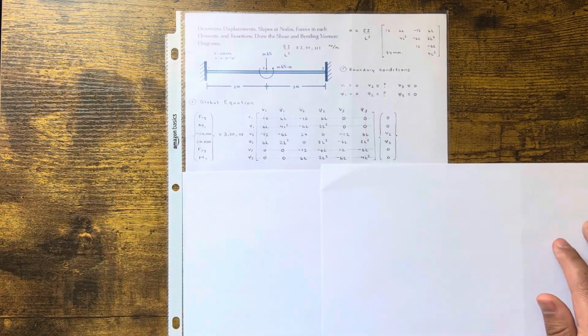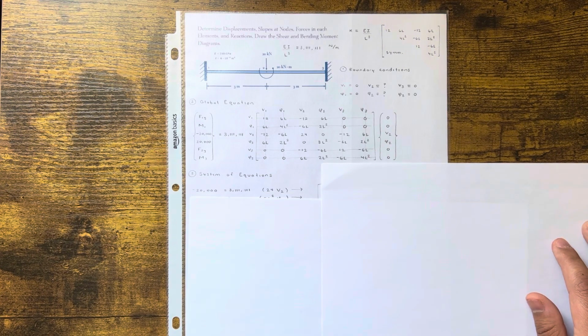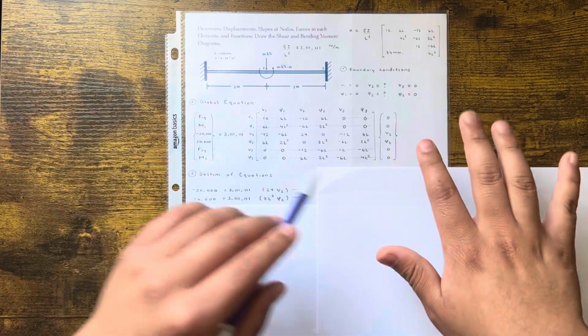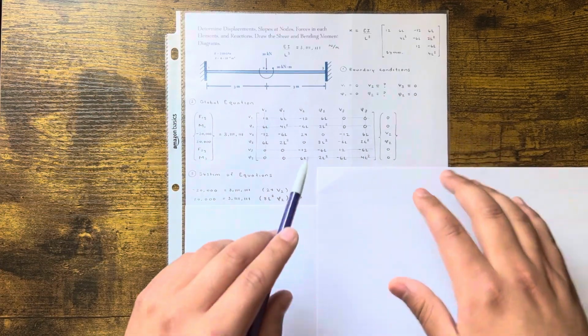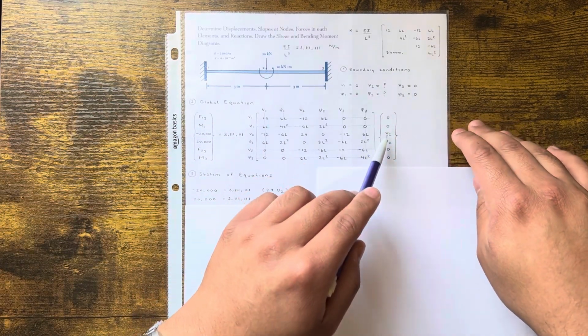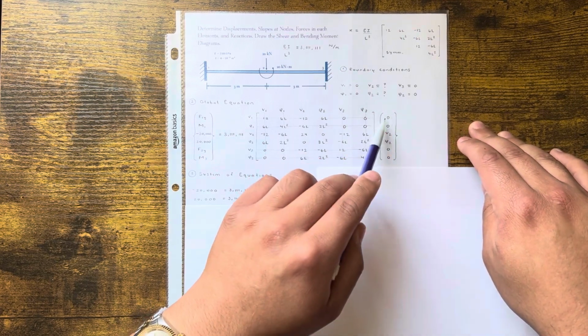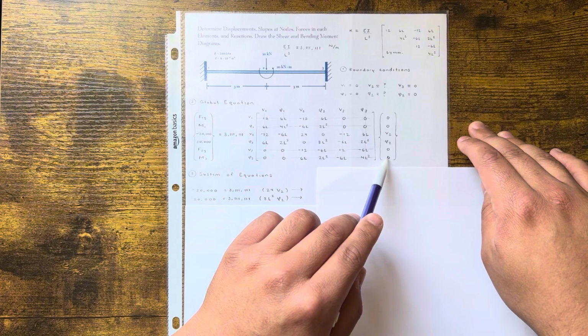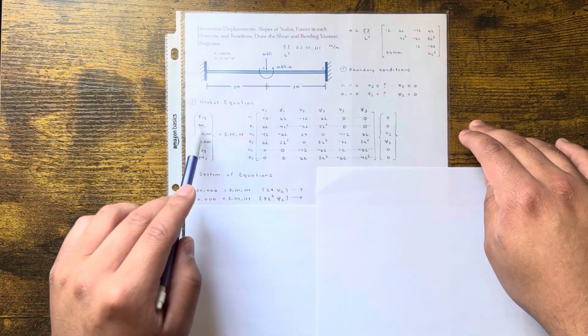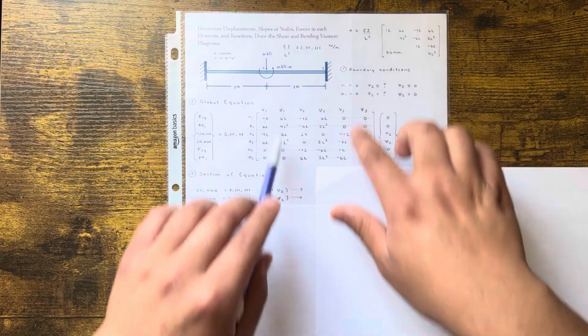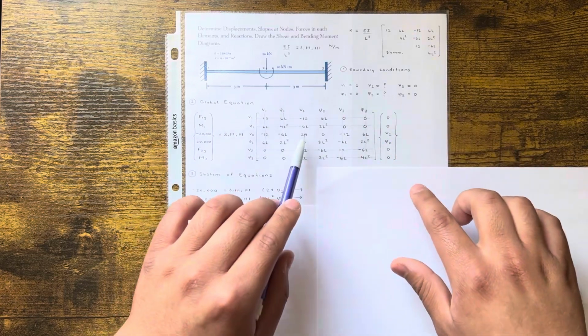Now let's go down to the system of equations. Once you have that part, you can start assembling the equation. For now, let's just focus on V2 and Phi2. First, you find these. Once you find these two, you'll know all your 6 displacement values, 1, 2, 3, 4, 5, 6, and then you're able to find the rest. So it's real easy. Just focus on these. That's why I crossed them out at first, once I knew they're 0.